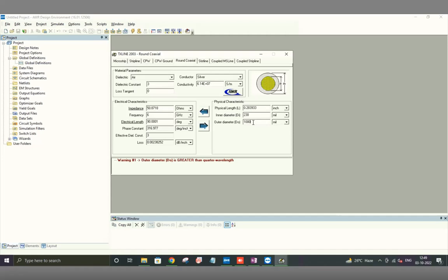I mean, it's arbitrary. You could have said that I should really not have the dimensions increase beyond 1/10 of the wavelength. So this quarter wavelength is just a cutoff they have kept as when the calculations are no longer going to be accurate. But you are right that maybe here a more accurate cutoff could be when the cutoff frequency of the TE mode comes within some percentage of the frequency you have specified here. So by the way, this is quarter wavelength at what frequency?